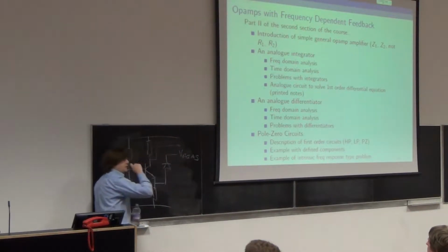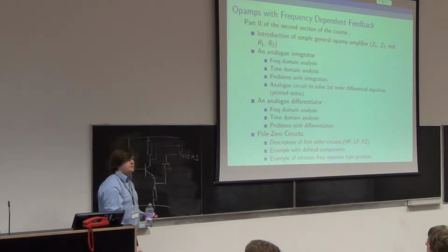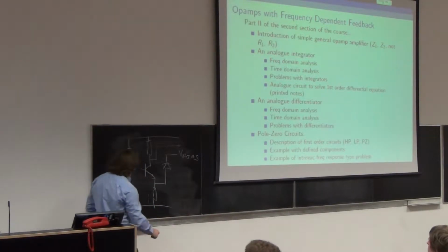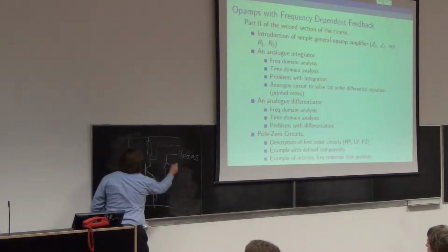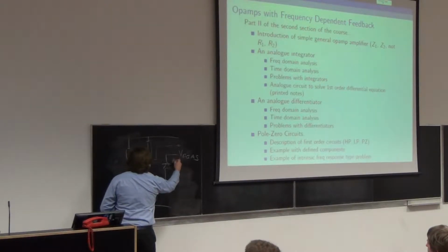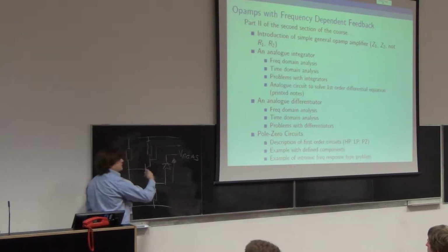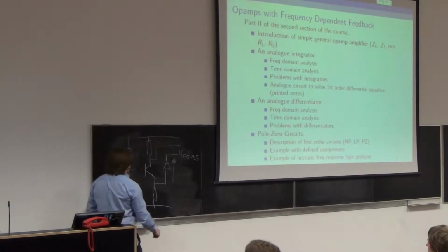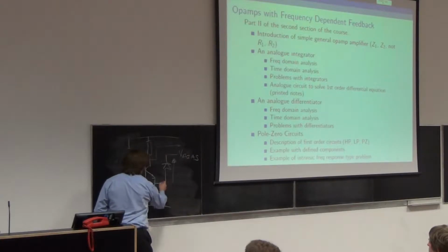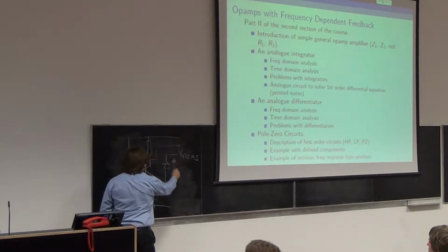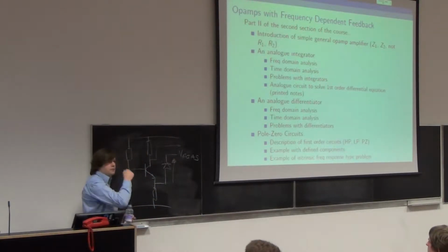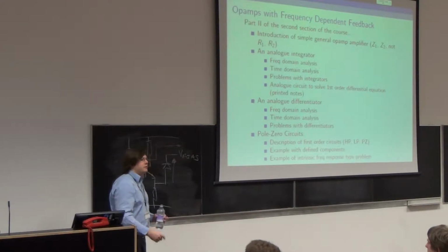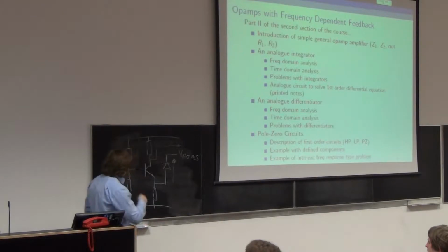And it'll go off to something else, maybe a really fast op-amp, maybe some other single transistor type stuff. I want to allow the person who uses this IC, this is going to go inside a chip, to put V bias on a pin on the outside, and then to know that this point is ground. So they know that whatever voltage they put there is the bias on the photodiode, because that will affect the operation of that photodiode in ways that we don't really need to go into.